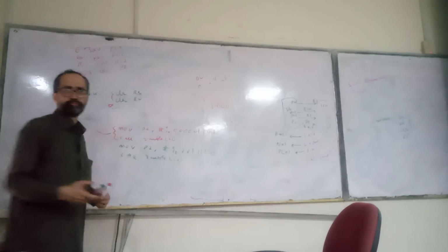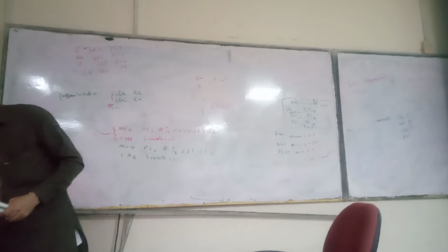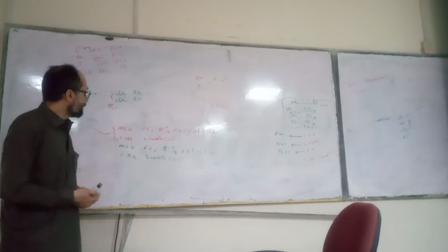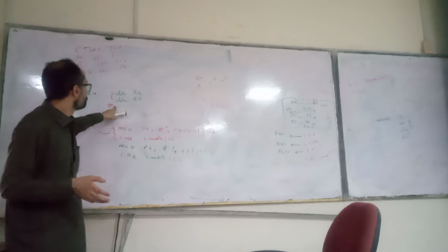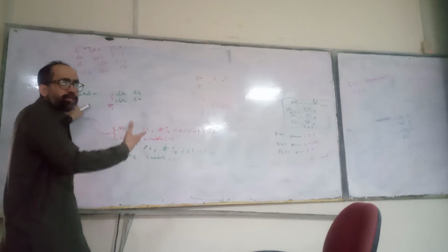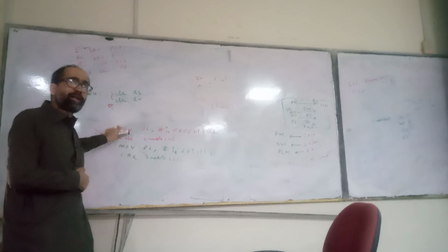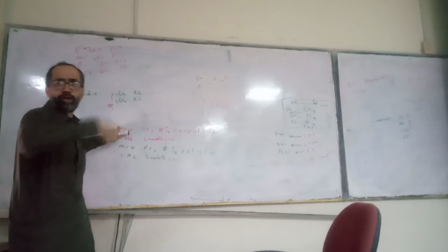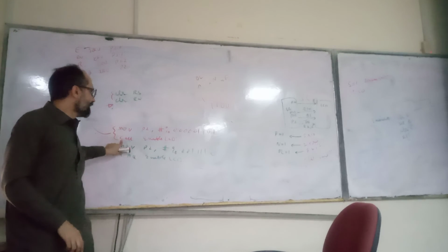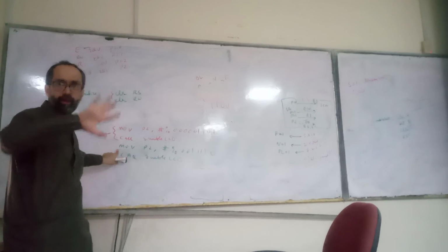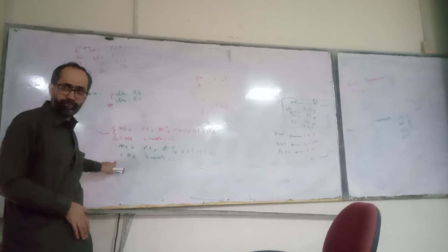Yes sir. Now we have configured it. What should we do initially? The program is initialized. We are initializing, we are configuring. We have clear RW and clear RS. First we said that whenever any character is displayed, it should also automatically move to the right. It's a one-time command. Enable LCD, then we configure it into 2 row mode. Call enable LCD.